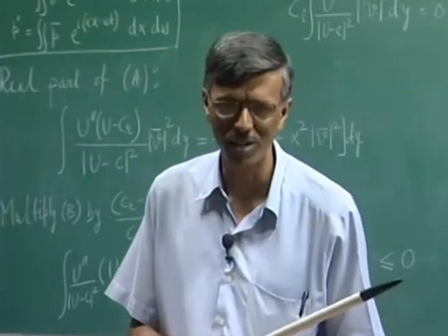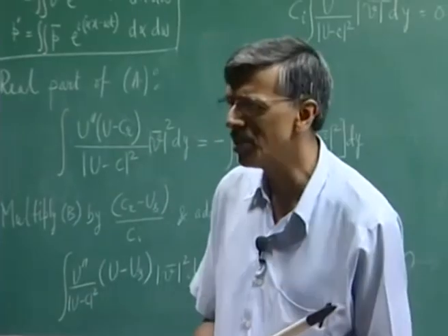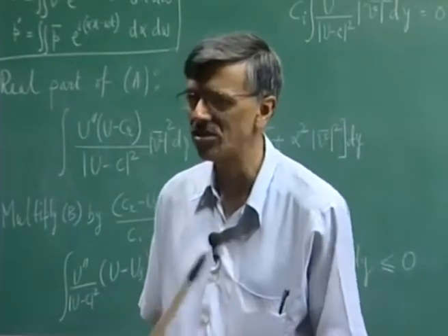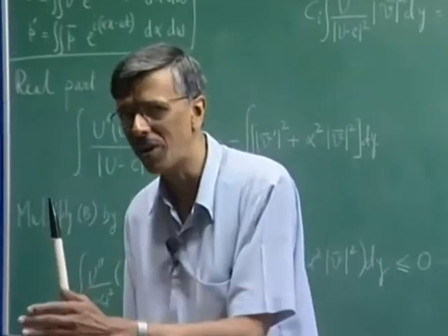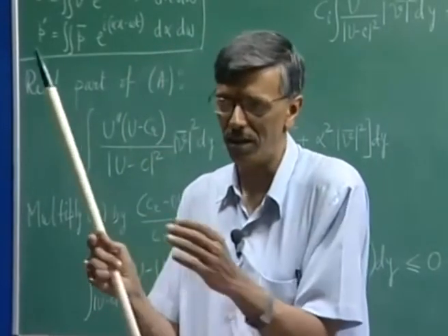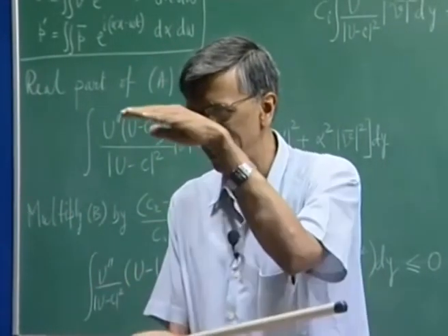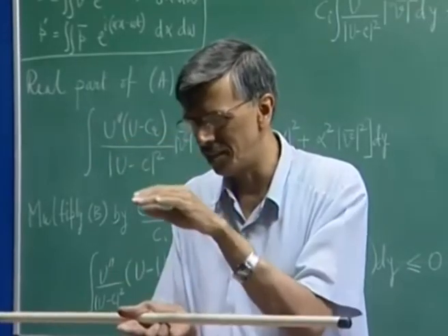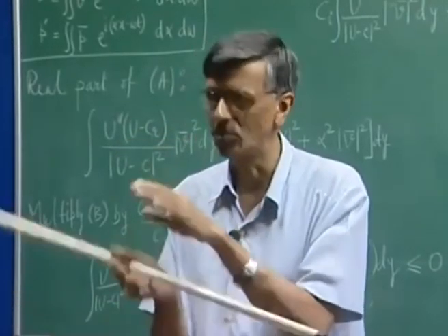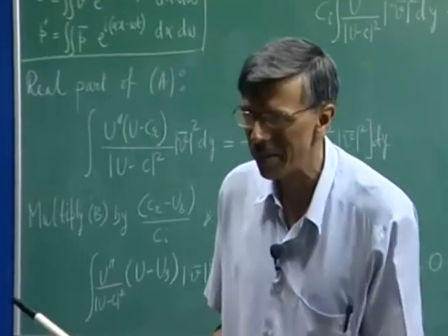We all know the boundary layer grows, right. But if the growth is negligible, I can still study the flow locally and say, look, if I am studying at this station, I take the velocity profile, the dependence on x is weak. So, let us omit that part.